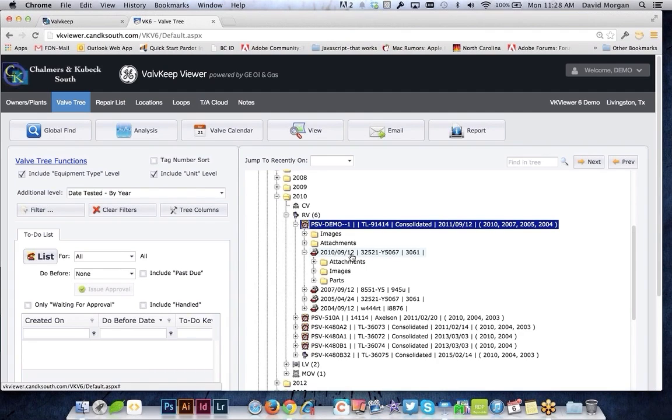So some of the stuff you can see, if I've got multiple valves in an application and I see that I've done multiple repairs on one where I've only done a single repair on the other, either that valve is new and was added in late, and I could tell that by the dates, or I've got one valve that's going to be a bad actor and I need to give it some attention to find out why this valve is failing and needing much more repair compared to other valves in a similar application. Lots of different things that you could do with the data we're capturing.